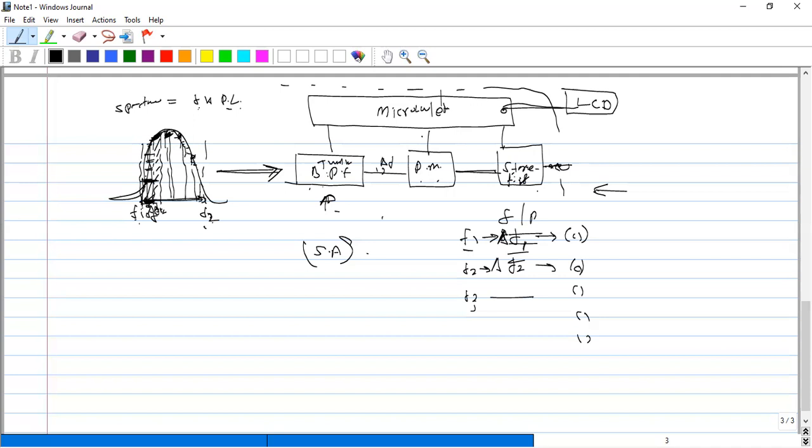So here you are asked to draw this signal. This is a sinusoidal signal. This is the frequency. You can calculate the one cycle time. Then you can draw this signal. Then you have to add some DC value. Then this signal will be shifted. There is no change in the period or the cycle. The same period is there.